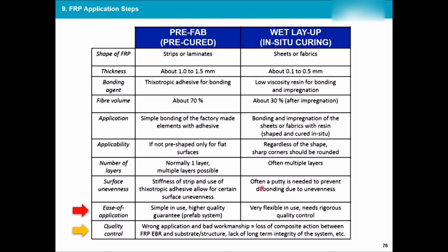Here is some comparison between the in-situ curing, which is the wet layup, where everything happens on site, and the prefabricated one, the pre-cured one, where the majority of the work has happened off-site. Let's look at the ease of application. When everything is already prepared, it's simpler to use, and much higher quality is guaranteed. When you have to do everything on site, you have to make sure the quality control is properly rigorous and that everything is going fine.